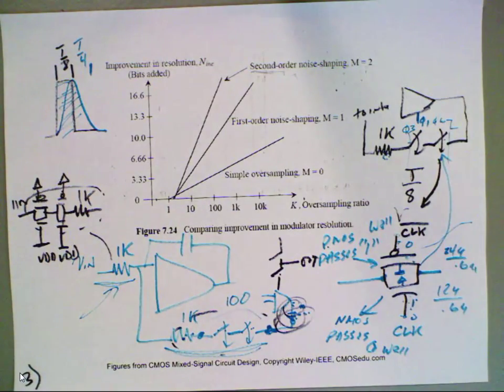But you don't want to do that. You want to pick what works for the fast and the slow. The problem is, if you do that, your slow isn't going to give you as good a performance, because you're being over conservative in selecting your clock phases. You can't change things, so you have to do it for the worst case. It's not optimized. Unless you can slow things down, there are going to be trade-offs. So you're going to say, well, if I do this, it works better, but if I slow things down, it works better if I do this. It's not going to be, this is the answer, woohoo. You know what I'm saying?